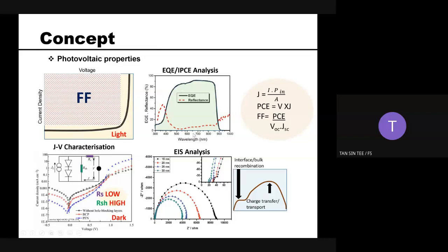The active materials that we use in our lab are P3HT and PCBM. P3HT always has very good absorption around 500 nm, which is in the visible region. That is why we plot a curve like this, because our absorption actually occurs from 500 to 900. This is the part where our exciton generation occurs and converts to the free charge carrier.